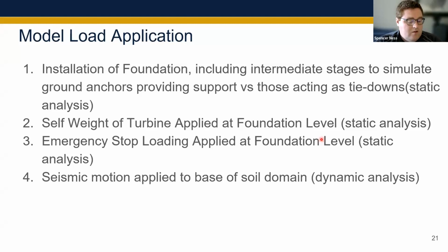So moving quickly here through our load application. Originally, we go through a series of intermediate stages of installing the foundation and installing these ground anchors. As I mentioned, some of them are serving as tie down, some of them are serving as support to the cap, so we need to make sure that those are being installed and designed and the loads applied correctly.